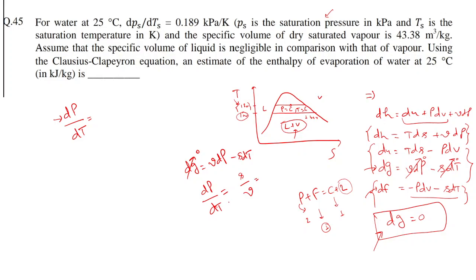Because initially you know the initial condition here. Here enthalpy you would be knowing, enthalpy of latent heat, even enthalpy of evaporation. This you would be knowing, right? And temperature is constant here only. So you would be knowing the SFG here only, right? What would be the SFG? HFG divided by T saturation, and the volume term means the difference of this and this, Vg minus Vf, and generally Vg is much higher than Vf, so we usually neglect it.